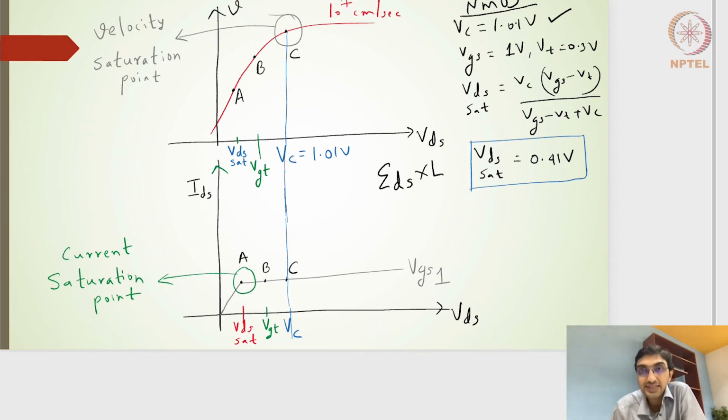If you remember the last time, we had the effective mobility of the NMOS transistor reaching around 96 or 97 values. And then the channel length was 50 nanometers. VGS applied was 1 volts. I don't think we'll require the VDS for finding out the VC critical voltage value.